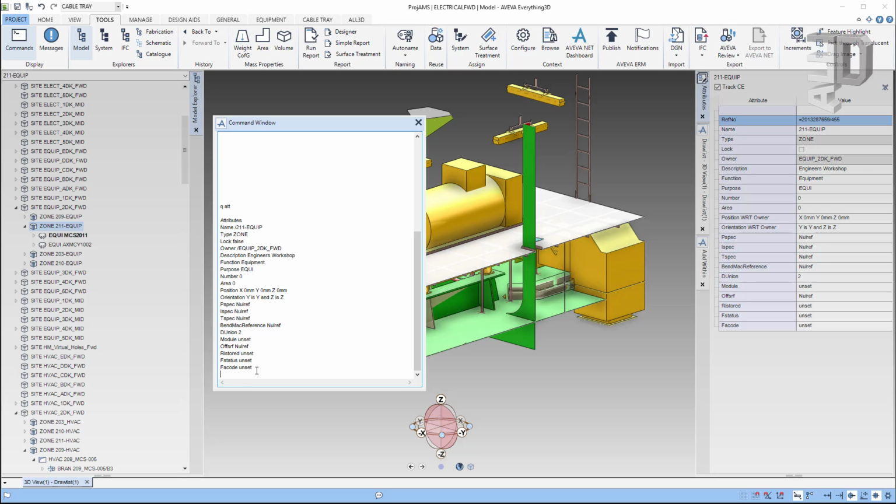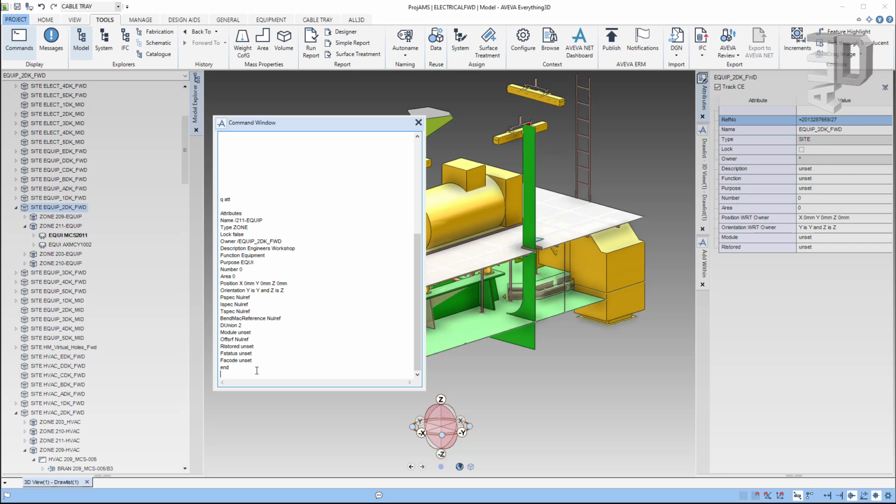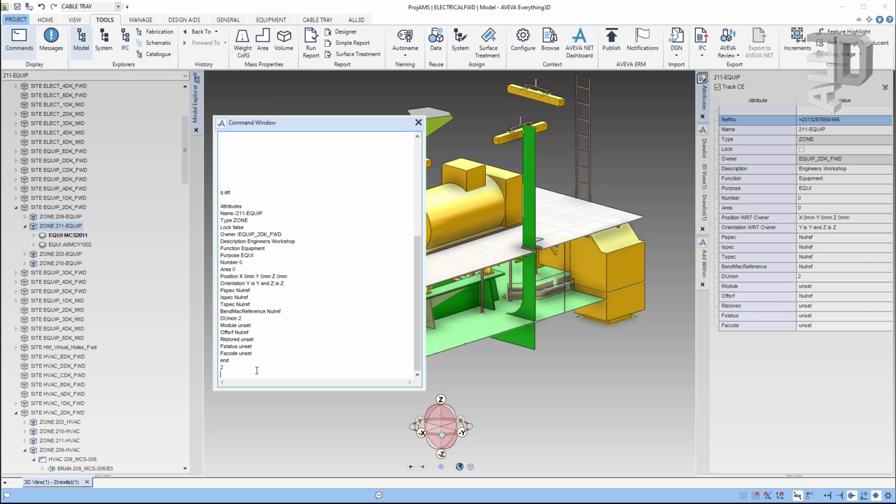Other ways in the command line to navigate are, for example, by and, or entering numbers for the hierarchies. For example, 2 is the second element in the hierarchy. It is also possible to enter the name of an element, but important is to write it with a slash in front of it in order to make it understand that you want to navigate to this element.